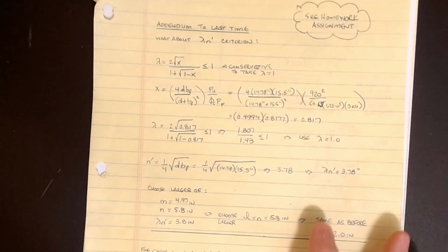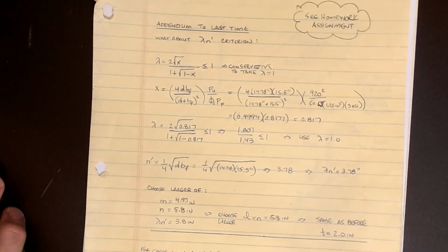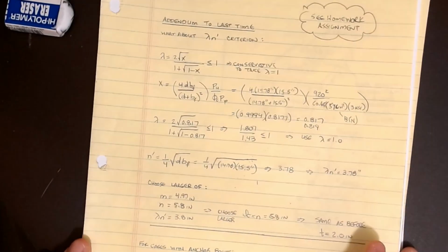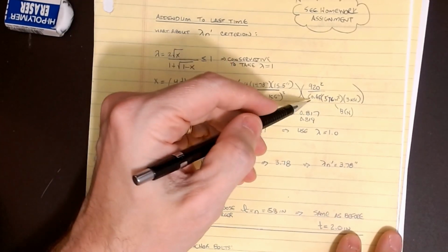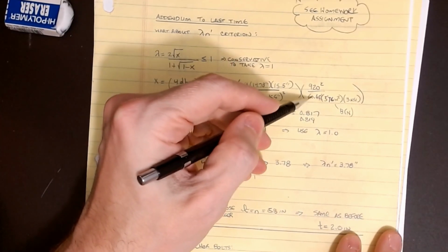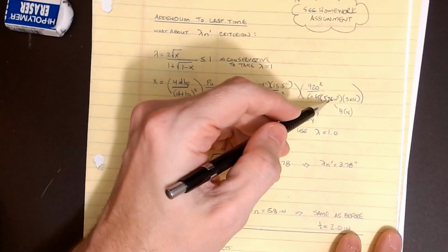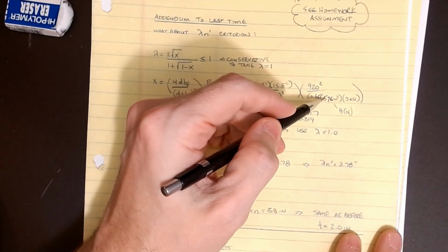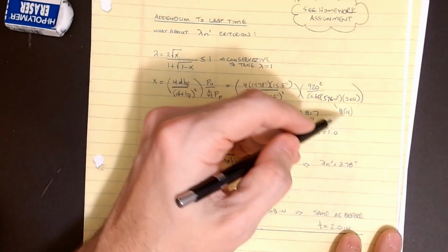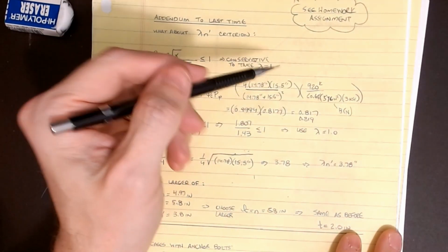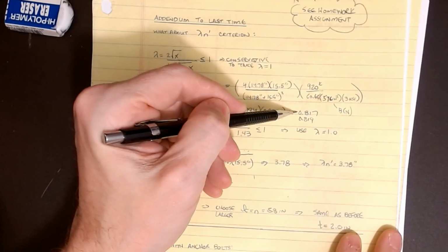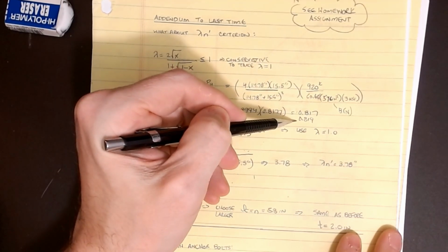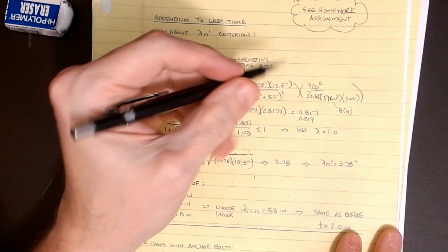Okay, in fact, let me double check that number now that I think about it. All right, so there was a little bit of an issue. First one was that I was using the old phi value. The current phi is 0.65. The other one was I was using the old b times n value of 25. Okay, in reality, it should be 576 for b times n. Now, the good news is that the difference, the old number was 0.817. The new number is 0.819 for those factors.